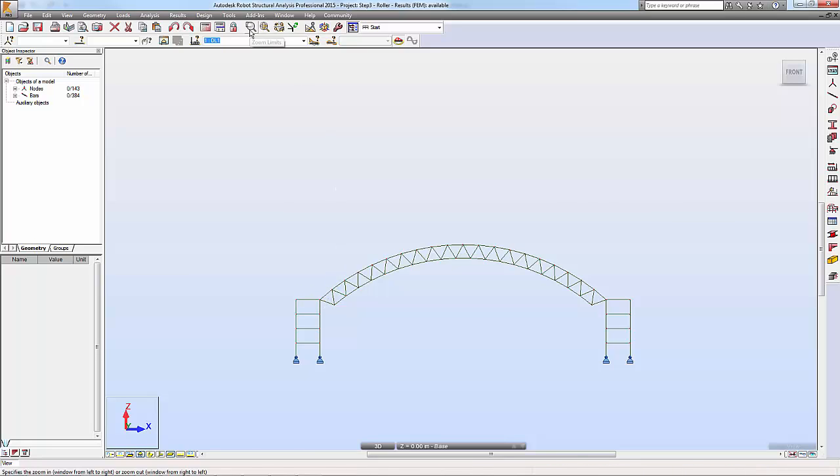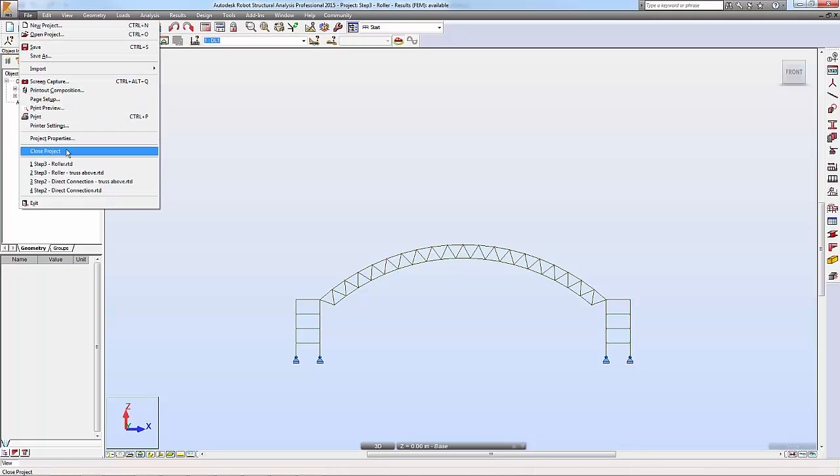That way you can control the spring to control the displacements of both structures. Possibly one of the most common things you can use: if you want a stiffer one, put a larger stiffness in between them, and if you want a weak one, you can put a small stiffness into the spring. So let's have a look at how we do that.